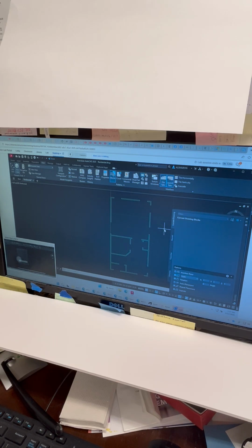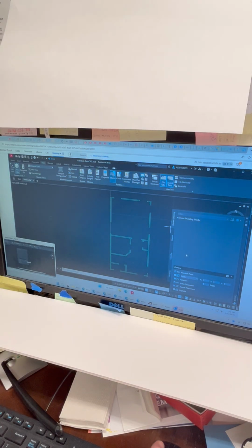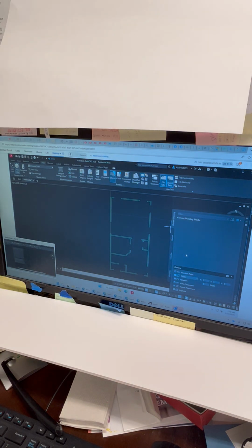What does that mean? Well, what that means is you're going to be allowed to pick a point where you want to place that block. And we're going to be placing the blocks at the little openings. So you want to have a little bit of freedom of movement to move around and pick those points. If you uncheck this, don't do it, but if you uncheck it, then it gives you some space here where you can add a coordinate where you want to insert the block. Now, this is useful for other types of workflows, like I want to insert a title block at 0, 0, 0.